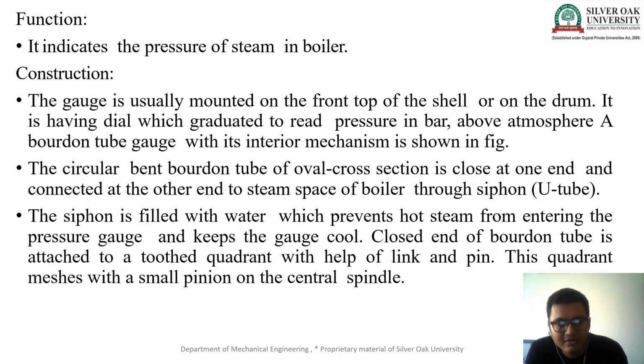So the close end of the Bourdon tube is attached to the toothed quadrant with the help of a link and pinion. We already discussed the rack and pinion mechanism is connected with the Bourdon tube. So this quadrant meshes with the small pinion on the central spindle.